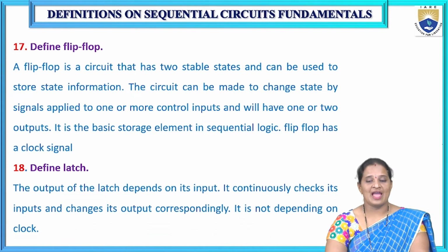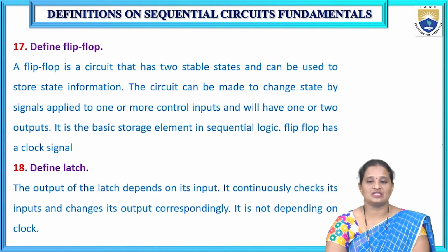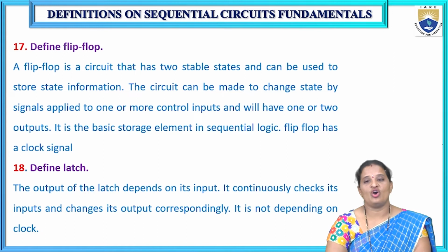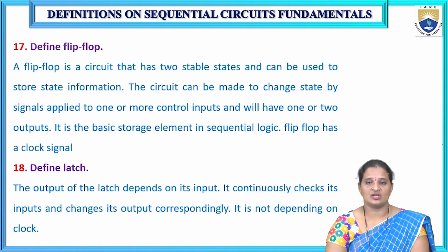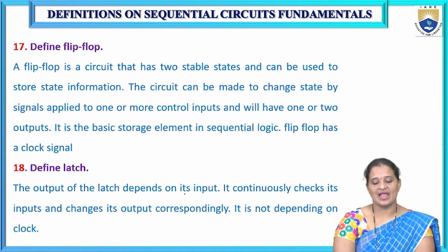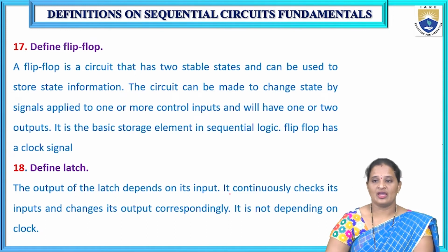What is a latch here? So the output of a latch depends on its input. It is continuous. It continuously checks its input and changes its output correspondingly. It is not depending on clock signal. So we can also say that a latch is also a memory element where it does not work in synchronous with the clock. That means it does not have any clock signal as the input, and the output of the latch depends on inputs only, whereas it does not require any present state.